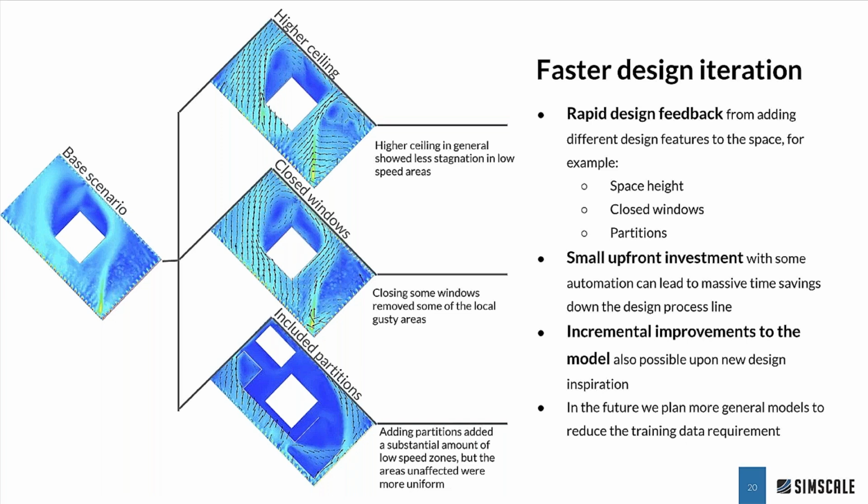And it's this that we would also be able to do in rapid succession. Make a change, maybe in Rhino, our favorite CAD tool, upload it to SimScale, get a quick prediction of what's going to happen, is it better or is it worse? I go back, modify, upload. So the process continues until very, very quickly we can iterate these designs to improve our end goal. Because in the end, we've only got so much time that we can allocate to these projects, and the more that we can do in that time, obviously the better the end result is going to be.